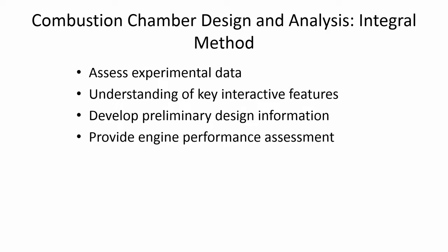to do the design. The integral analysis is mainly used to assess the experimental data, understand the key interactive forces and features, develop preliminary design information, and provide engine performance assessment. Even if they are 1D or very rudimentary, these integral analyses are extremely important and must be carried out before going into any sort of complicated analysis.